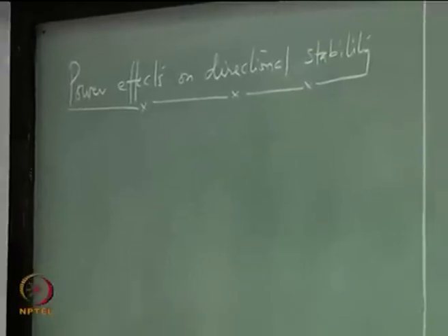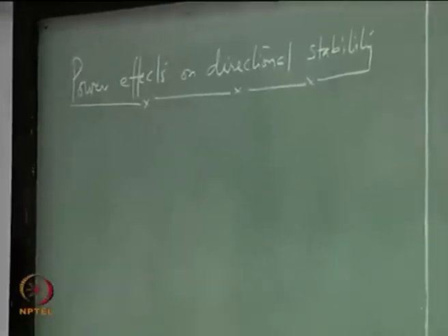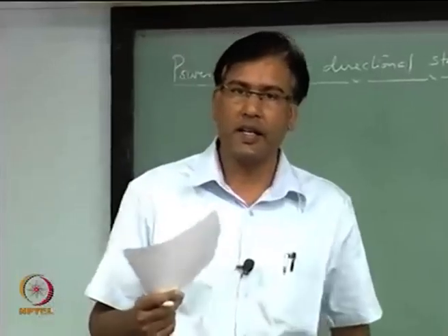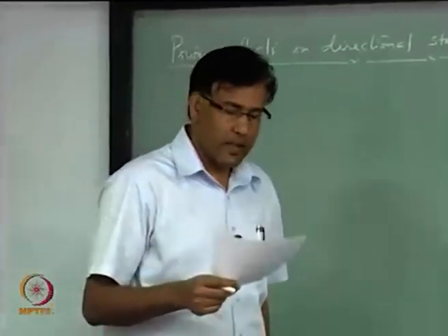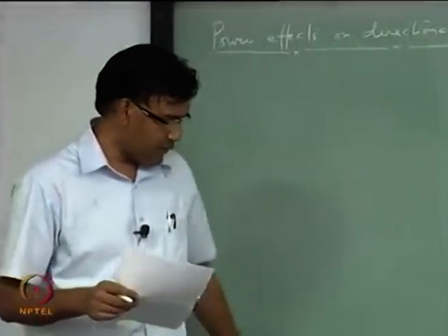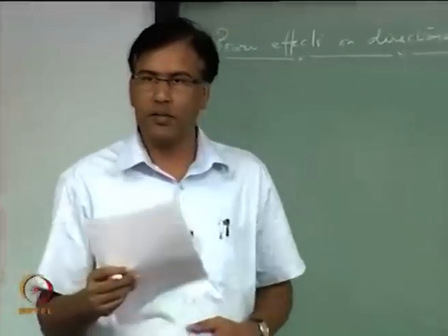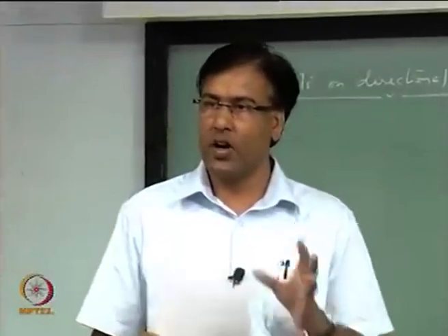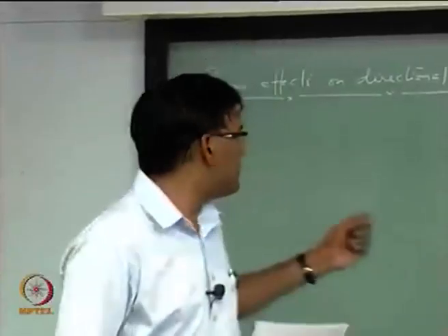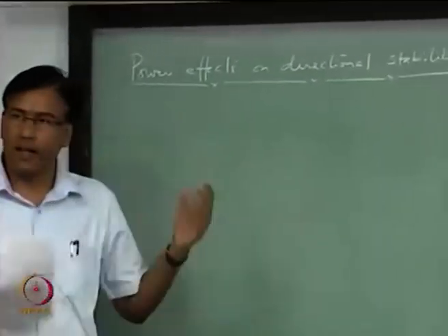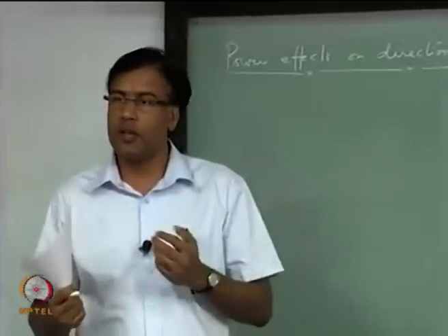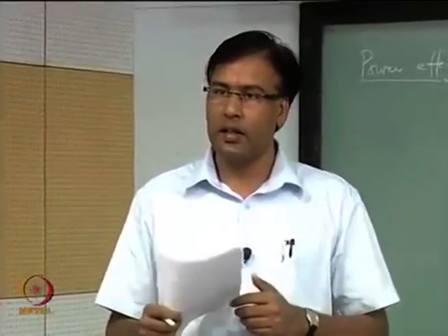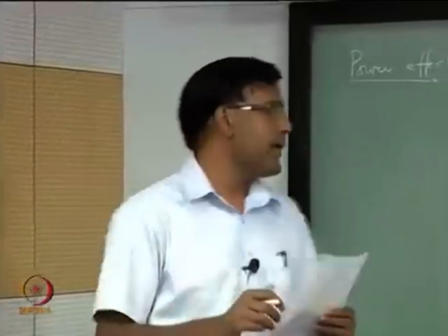Even though we have some information available in the book by Phillips and in Perkins and Hayes, most other textbooks will talk about the difficulties involved in finding the contribution of indirect effects of the propeller on delta Cn beta and Cl beta, right.